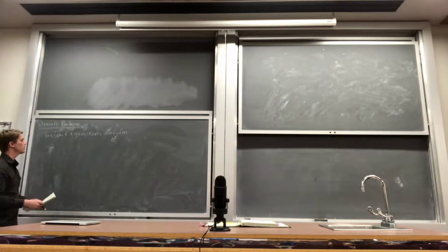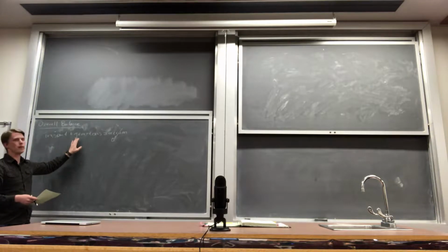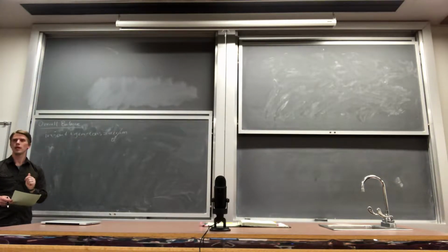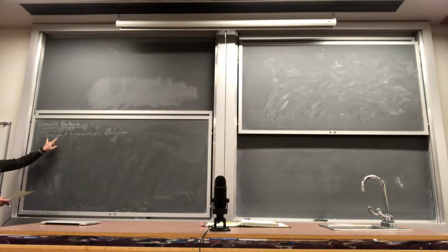For a material balance, we can get rid of generation, we can get rid of consumption. For an energy balance, we can get rid of generation, we can get rid of consumption. For mole balances, we have to keep these 2 terms. So most of our attention has been focused on just these 2 aspects of the process.